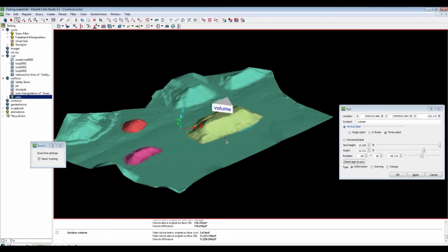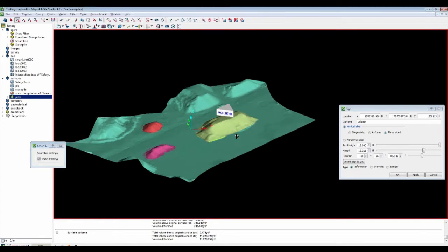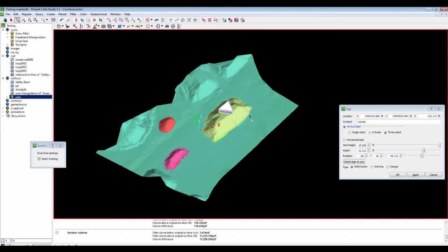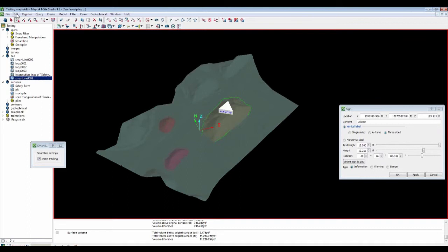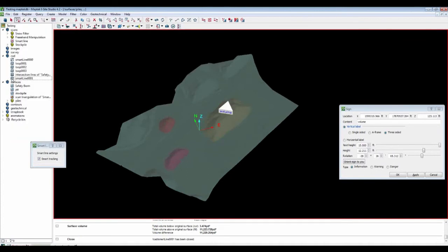If I were to use the Smartline, trace around the edge of this, let's see here. So if I did that, and it wasn't closed, you see how it's just a line there? There's this option under the Edit menu. So you hit Edit Close, and then now I've got a valid polygon that I can project to my surface. So you can use either tool to create them. You just want to make sure that it is closed and that it actually wraps all the way back around.